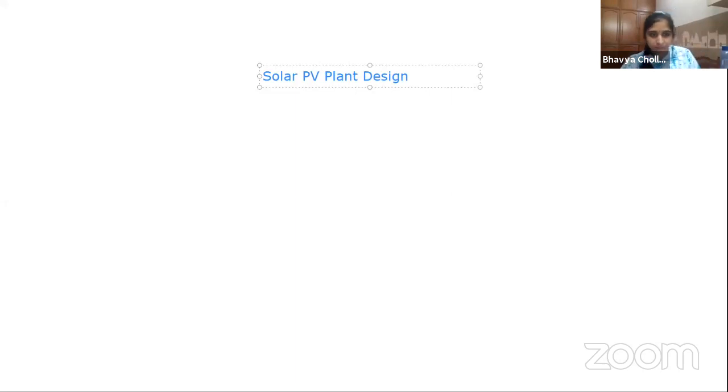Right. So we were talking about the solar PV plant designing consideration. In terms of the electrical aspect, we generally start from the irradiation level consideration along with the complete meteonorm data, and then you design the string configurations based upon your area consideration, module selection, inverter selection criteria, and everything.